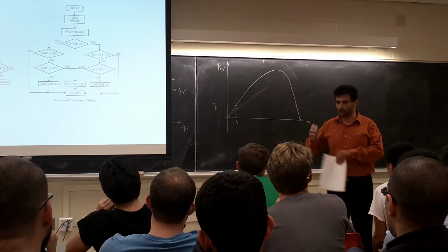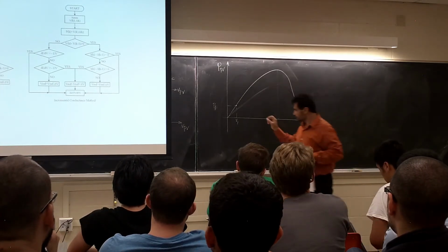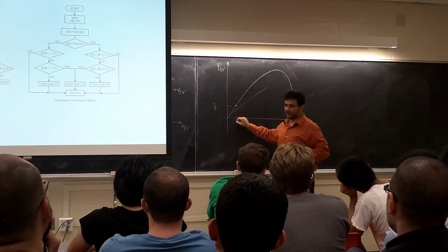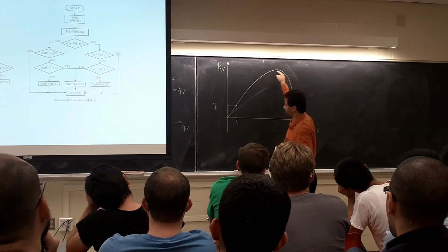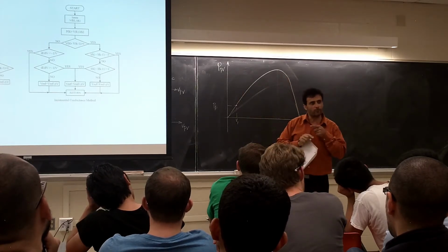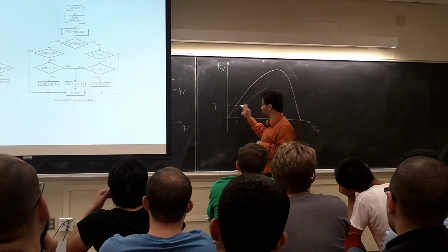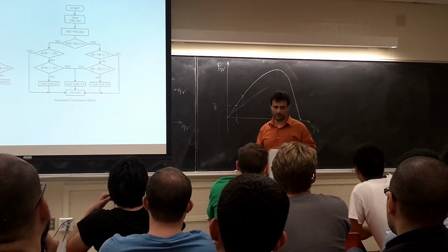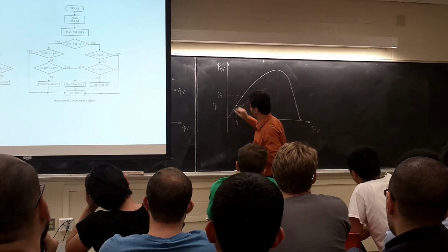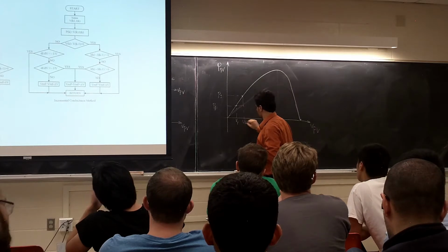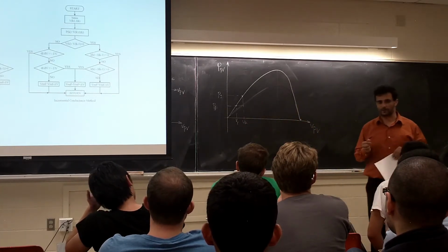The first time, let's say I increase, right? I'm going to go in the right direction. So for example, we set the voltage of the PV to 10 volts, but let's say here it is 16 volts. I say go 1 volt higher, right? I'm going to come here. If I go 1 volt higher, my new point is going to be here, which means this much, P2 and V2. Can somebody tell me? The next one I can go smart, it's not blind anymore. Can you tell me how?